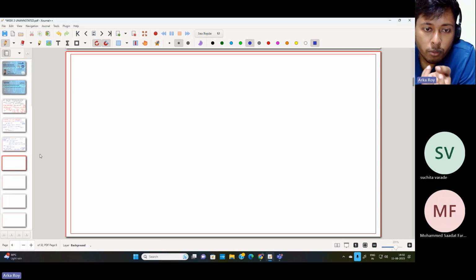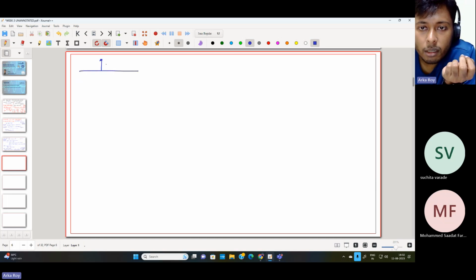And we also have to see whether this is time invariant or not. So for example, I am applying something like this. This is my signal x of n, and I have switched the signal on from n equals 0. That means it is a causal sequence. On the left hand side, for all the negative n, there is no component.